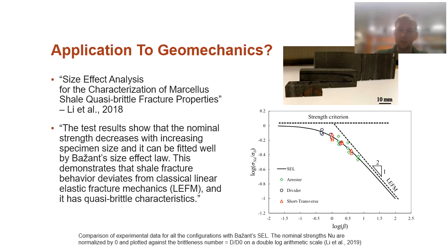I mean, from these results here, if you were to test a small piece of shale in the lab and you were to say, hey, the nominal strength is this, and then you took it to mine scale, well, your nominal strength would have decreased dramatically as you were to scale up. So this is an important area of study. I just wanted to point that out here in this section. And I'll encourage you, in a little bit here, to read deeper into the study and take a deeper dive into where we can use this in the real world, because it is pretty important to notice the differences between lab scale and field scale for geomechanics and concrete.